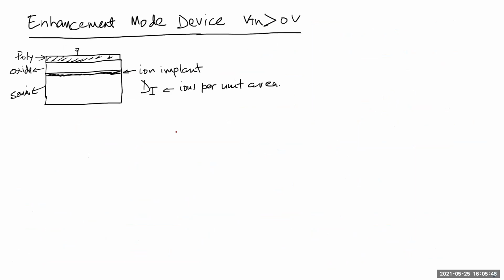So for the enhancement devices, what people do is, obviously you can't change the poly, you can't change the substrate. I mean, you can change the diffusion constant and all that, but in your typical cases, if you try to change those, then it'll become very conductive, and the rest of your devices will just become really bad devices. So instead, people dope whatever is needed for your resistivity, for your isolation and all that. Poly, same thing. And then once you do the calculation, like in the previous calculation we did, we find out it's negative. They do a positive ion implantation here.